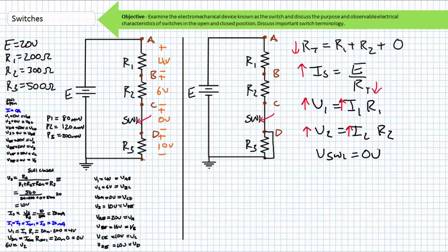I'll kind of neglect the closed switch for the rest of this problem, since that's really the purpose of a closed switch. It enables current flow, but otherwise in no way influences circuit analysis. Current ordinarily intended for R3 is routed through the 0 ohm short instead. With no current flowing through the shorted R3, there should be no voltage drop across this shorted component.